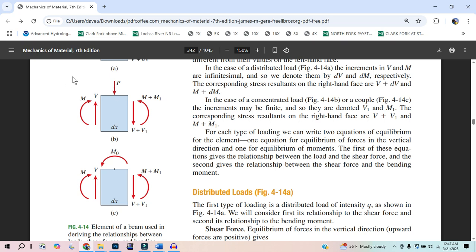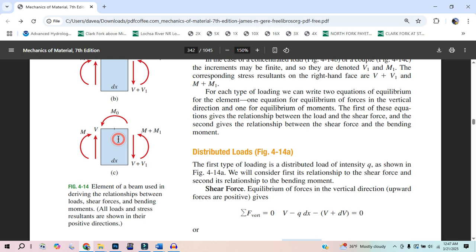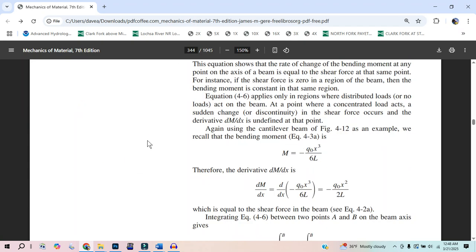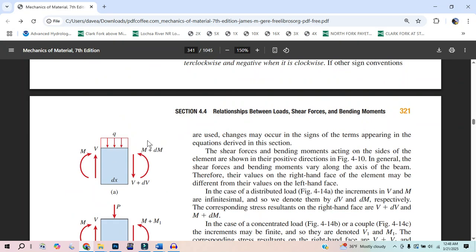Well, yeah, I can do it. If you have a beam and you put the load in the middle, the moment's going to be 0 at the end, max at the top, but then it changes down. It's not continuity, but as dx goes to 0, the moment on this side is the same as the moment on that side. So how does that work out? It's just that the slope changes. I don't have that 100% right, but here you actually get a jump in the moment. So there you go. I think these are probably the hardest things to wrap your mind around, and it goes into it.